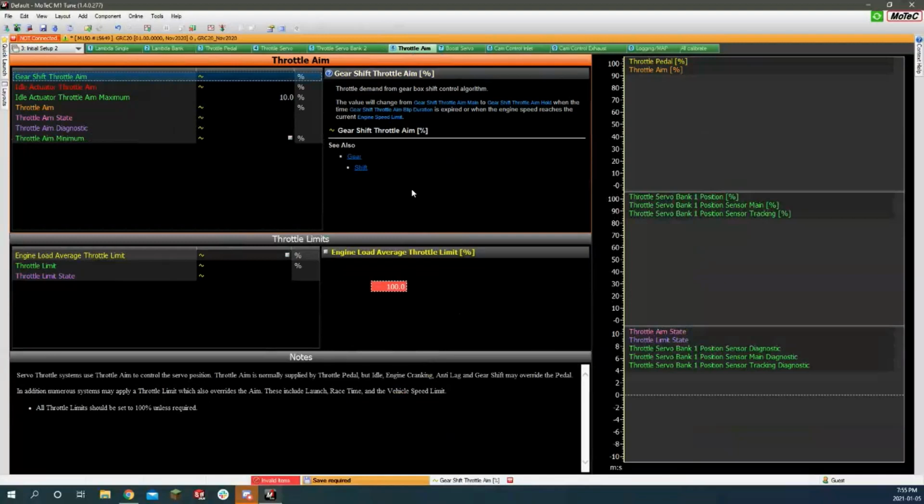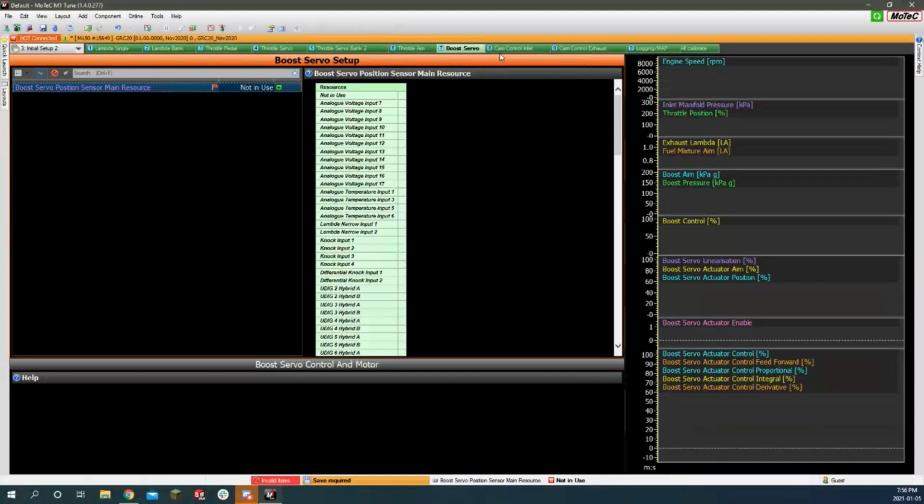There are lots of different things about the throttle, and it allows your engine to idle better. It allows you to blip the throttle on downshifts or upshifts if you're off power, which is another thing we'll get to in a sec. But electronic throttle is really good. It takes a lot of setup in the ECU. There's boost. We don't have a turbo.